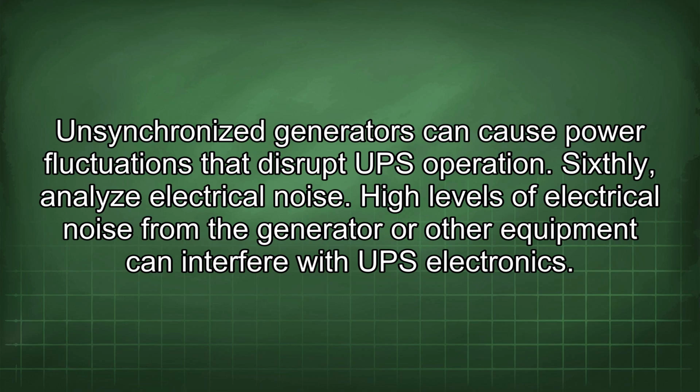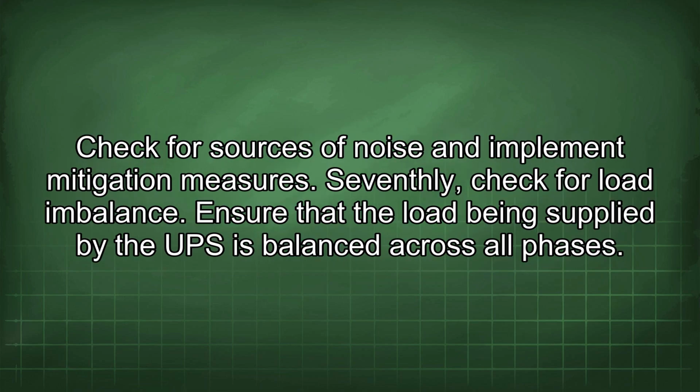Sixthly, analyze electrical noise. High levels of electrical noise from the generator or other equipment can interfere with UPS electronics. Check for sources of noise and implement mitigation measures.